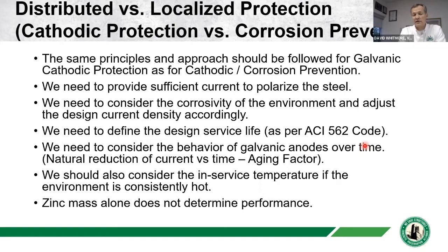But because they're zinc-based anodes, there's really pretty low risk. You're not going to have any issues with hydrogen embrittlement or those kinds of things that you might otherwise run into if you run an impressed current system too high. I'd say the biggest risk is that you waste money unnecessarily.